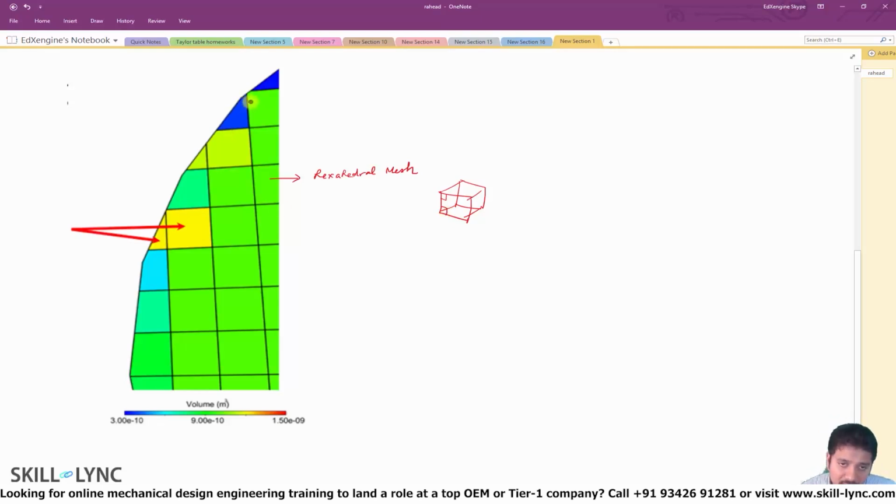Now on the other hand, if you look at this particular cell, this is what you call a cut cell. Now you can see that it's cut in such a way that it represents the boundary accurately. All right. So if you remember, when you start with a CONVERGE simulation, you load an STL file, correct? When CONVERGE creates the cut cell Cartesian mesh, it uses the information from the STL file to create these cut cells. Now these cells are called polyhedras. Just like you have polygons in 2D, polyhedras are 3-dimensional structures which can have multiple faces. So for example, in this particular case, if it is 3D, it can be like a wedge. Similarly, you can have more complex shapes.